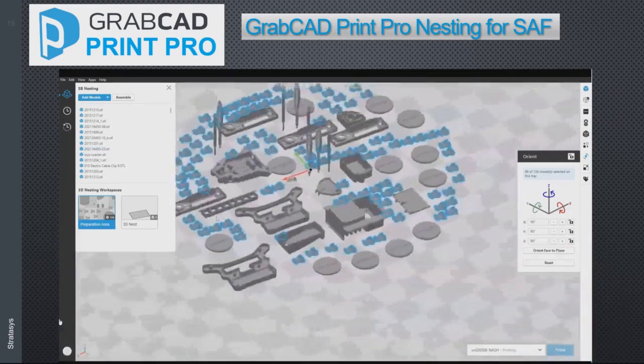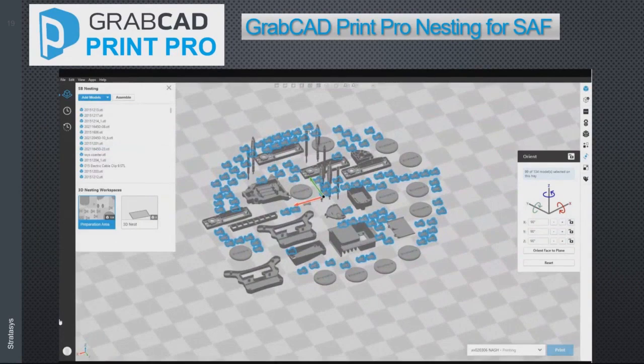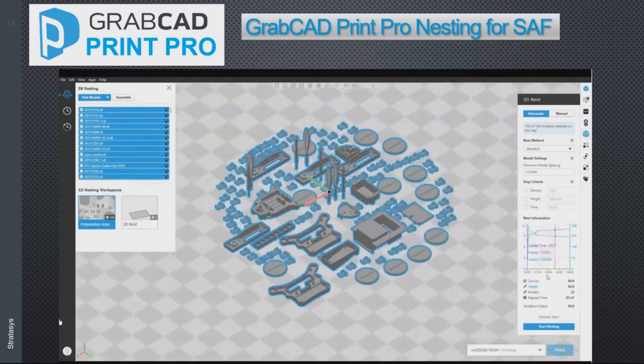Here I'm going to show a little demonstration of how GrabCAD Print Pro works with our H350 SAF machine. The SAF machine is a powder bed fusion machine, so it builds like a large vat of nylon powder. In the past we actually had to have a third-party software to do the nesting to pack all the parts into the build chamber, but now with GrabCAD Print Pro we can do all of that in one software. So we can do all of the nesting and the build processing and the time estimation all within a single software. So we have a big pack of parts here, and we're going to nest it together.